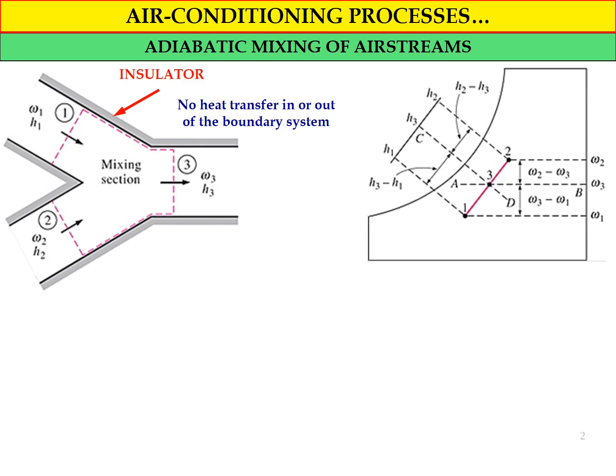Okay, if we draw the process on the psychrometric chart, as shown in the second figure, we have state number 1 and state number 2. The main criterion for state number 3 is that if we draw a line connecting state number 1 and state number 2, the position of state number 3 will be on the straight line connecting them.